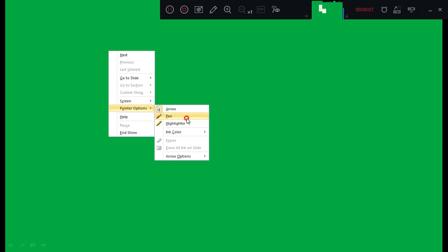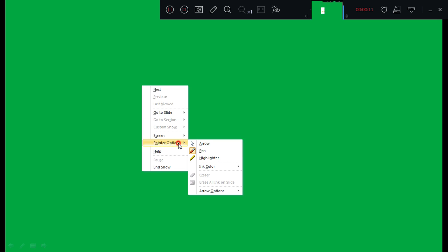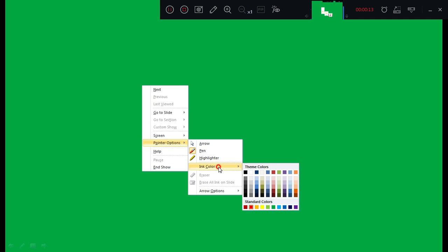Afternoon, students. So in the last class we discussed the binary ripple counter, right? Which is also called an asynchronous counter, right? Why is it called an asynchronous counter? Because the output of one flip flop is given to the control input of the next flip flop, right?